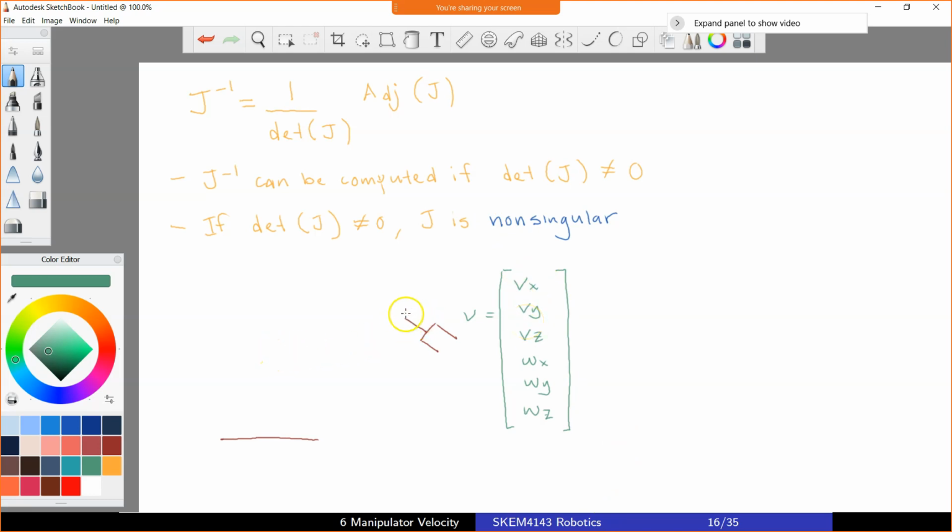If you want to use the end effector to pick and place an object in a 3-dimensional space in various poses, then probably you need all 6 components, because not only do you have to move your end effector, you also need certain orientations of the end effector. So you need all 6 components.